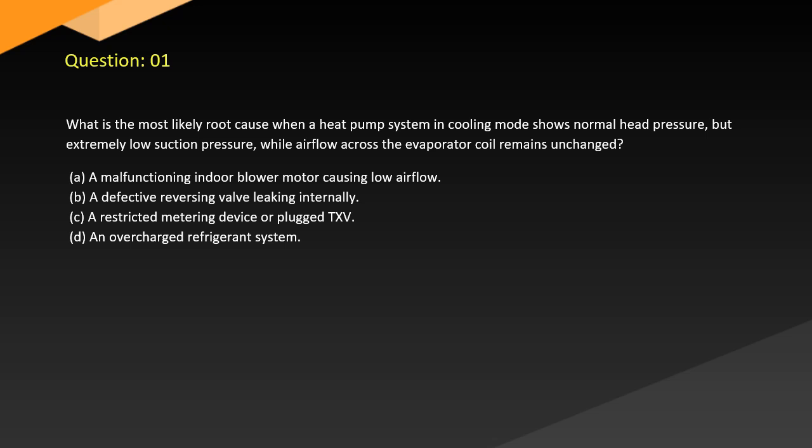Question 1. What is the most likely root cause when a heat pump system in cooling mode shows normal head pressure but extremely low suction pressure while airflow across the evaporator coil remains unchanged? A. A malfunctioning indoor blower motor causing low airflow. B. A defective reversing valve leaking internally. C. A restricted metering device or plugged TXV. D. An overcharged refrigerant system.